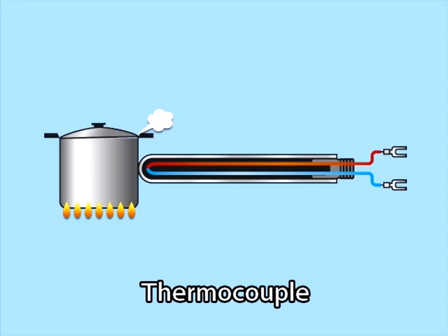When two types of metal wires are connected to each other at the ends and heat is passed to the contact point, voltage is generated. This phenomenon is called the Seebeck effect. The thermocouple measures the slight voltage generated due to the Seebeck effect and converts it into temperature data. The ends of some thermocouples are covered with stainless steel sheaths to strengthen the metal and protect against corrosion.